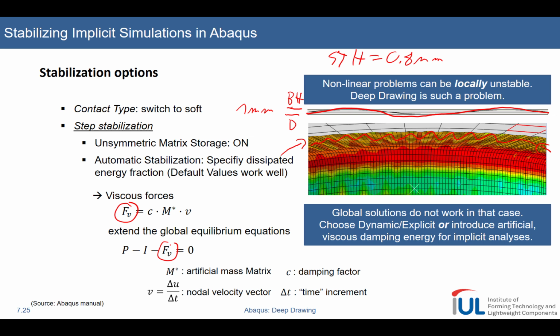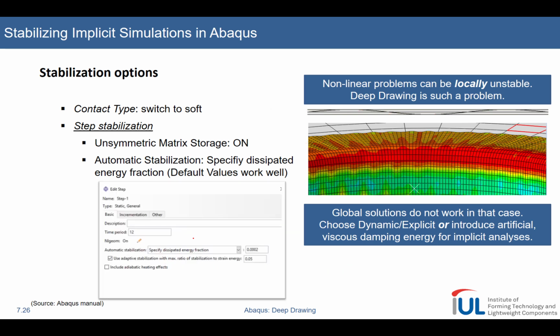So you treat these local problems, because it's a vector, this force vector only applies to the nodes which cause problems in your overall global system. So that's a pretty neat thing to do. However, think about it. If you add some artificial term to this equation, it's not your true physical equilibrium anymore. We'll come to this later, why keeping this in mind is very important.